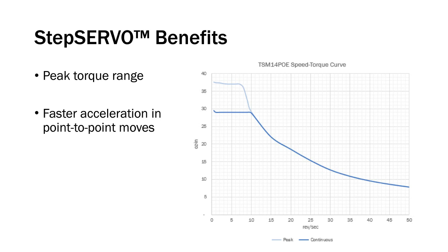That would qualify for PoE plus. If you had 4 ports at 30 watts each, that would be 120 watts. But the power budget on that switch might only be 100 watts. So what that means is that you might only be able to use 3 of those PoE plus ports at any given moment for our motors.